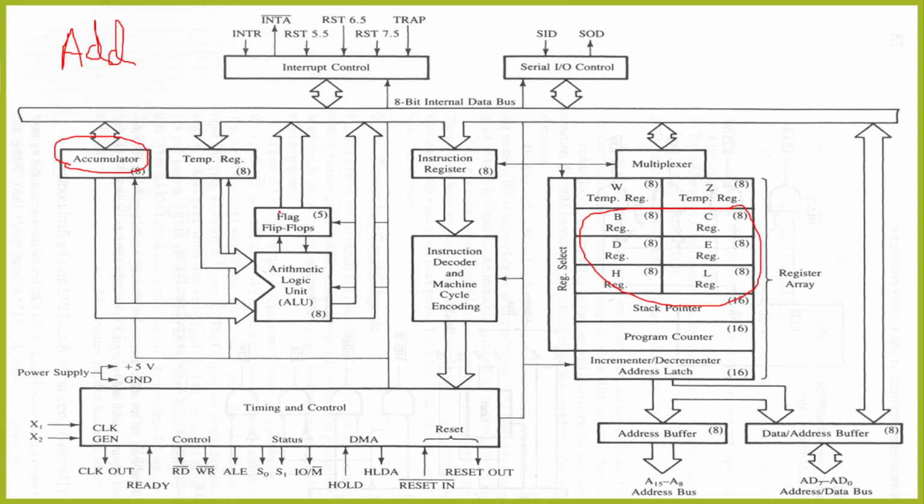So we will discuss flags in detail next. Then there is a temporary register. It is acting as a buffer, because when we take data from external memory, it will take some time to release. So that will be transferred to temporary, because when the arithmetic logic unit is performing arithmetic or logic functions, two data should be available at the same time, so the temporary register will enable. This is a system resource register, not available for the user. That's why no name is given for this register.